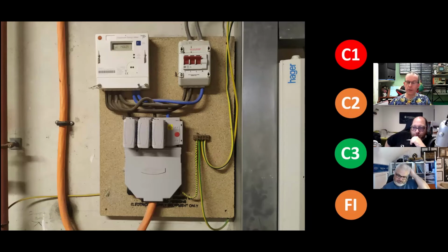And unfortunately, the flats that are on the same phase as the lift, the lights go quite dim when the lift starts. So no surprise there. And I think it's 11 flats in this building, and they've got basically 2 of the 3 phases kind of distributed between them in a not very even fashion.